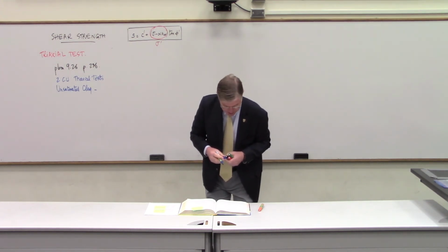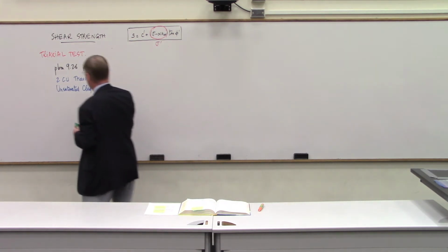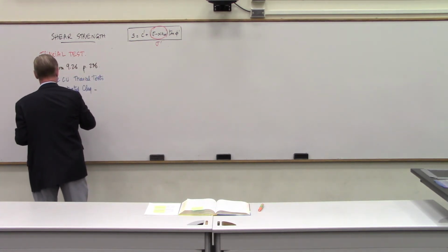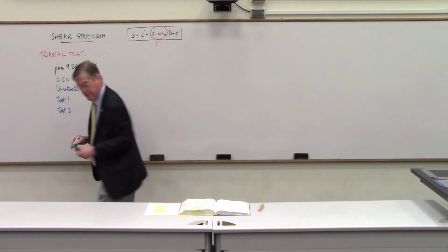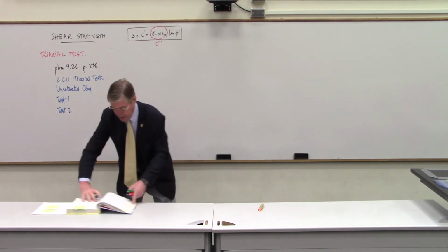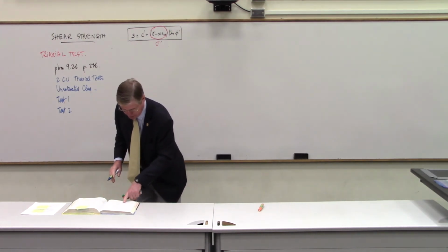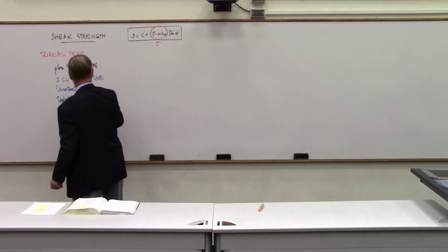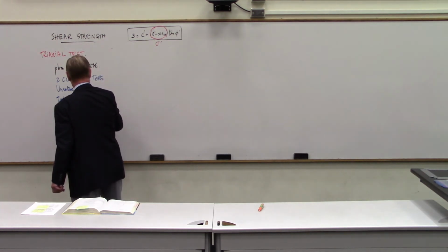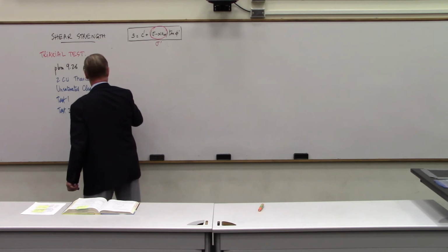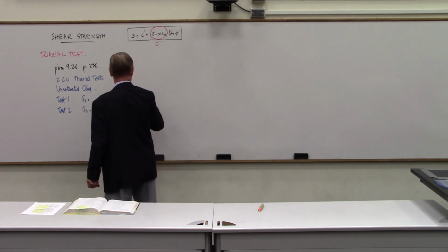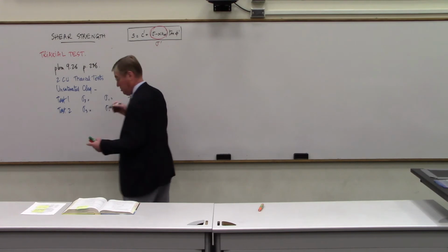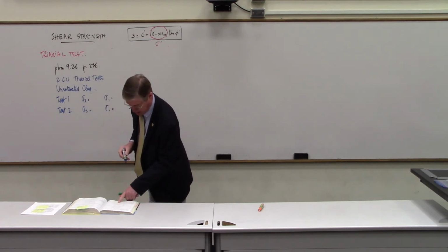The results are as follows. So I'll repeat this. Test 1, and then test 2. And we're going to have to look at sigma 3, sigma 1, and then we're going to have some information on the degree of saturation so that we can use that to estimate the water area ratio.